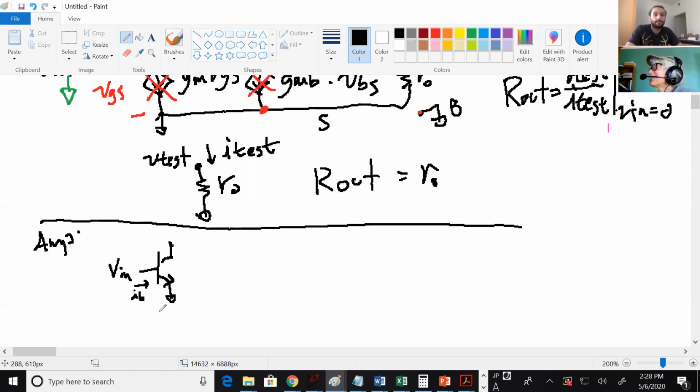Second one is that then I can treat MOSFETs and BJTs the same. And also that if you treat this as a voltage input amplifier, you get an exponential change in current, and so you get an exponential change in V out, since you're throwing that current across a resistor for, say, a common emitter. But if you use it as a current amplifier, IB gets multiplied by a constant, whatever beta is. So you don't get that exponential increase in current. But you can treat this as a current amplifier.